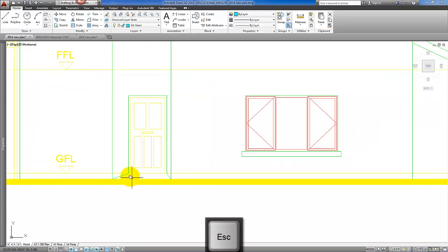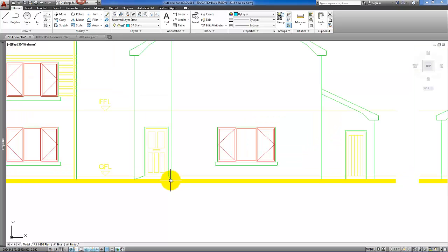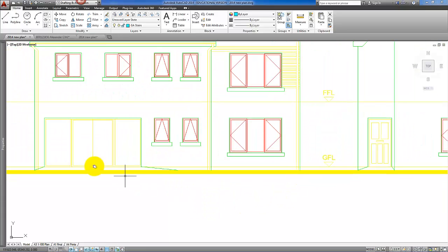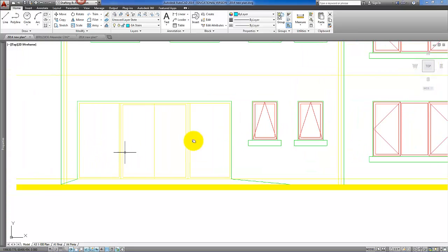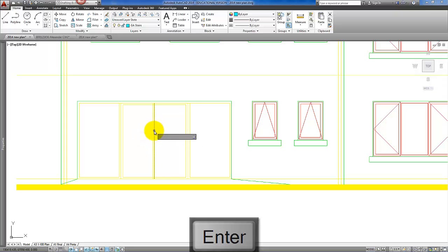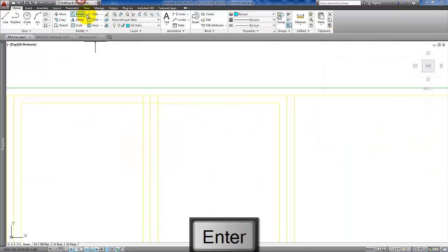And please note that with the likes of the front door there is a slope. Because there's level access required under building control, you should be showing the slope lines at the doors. And again, at this door window assembly here, we have the double doors that would open in the middle. Technically there really should be something of a frame in the middle part of that door as well. So we'll just trim that out a little bit to try and see roughly what that would look like.